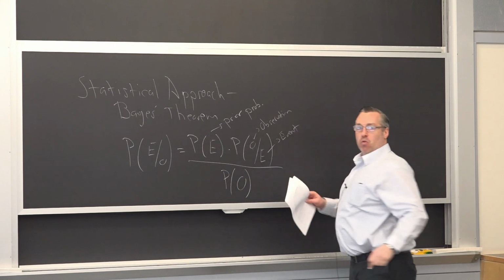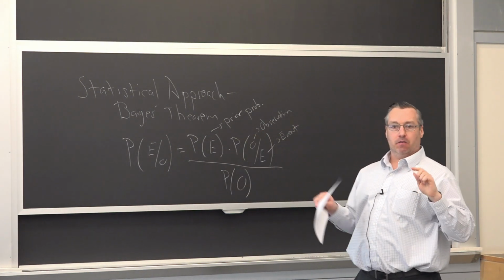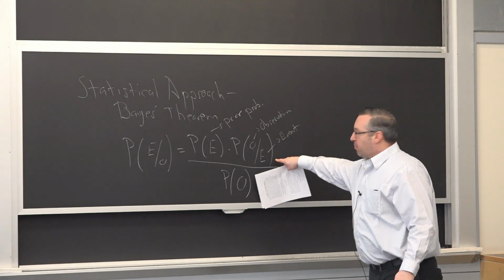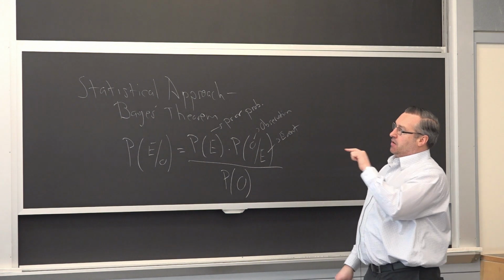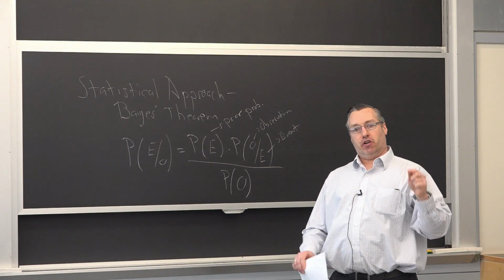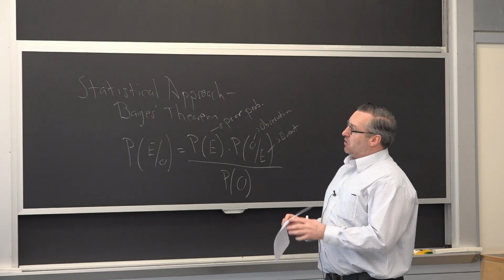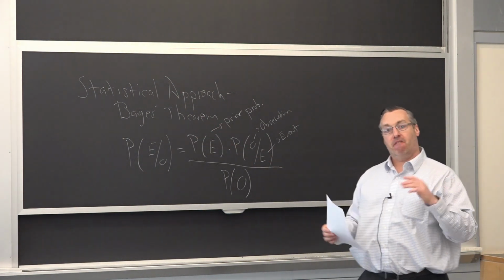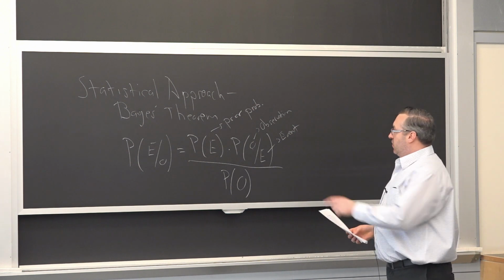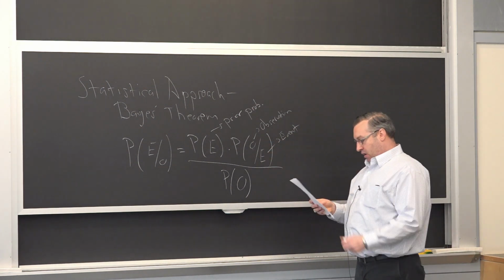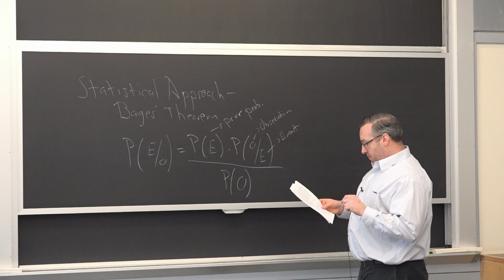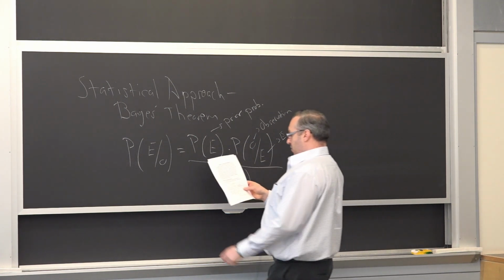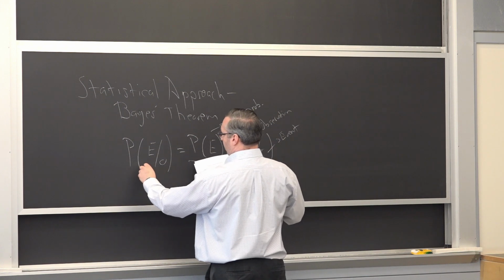And that's what differs when you look at your various POD models, fracture mechanics models. Your conditional probability depends on which application, which industry. Are we talking aerospace? Are we talking transportation? And that's where your material properties play a very big role in changing these values. So ultimately, you have the posterior probability.